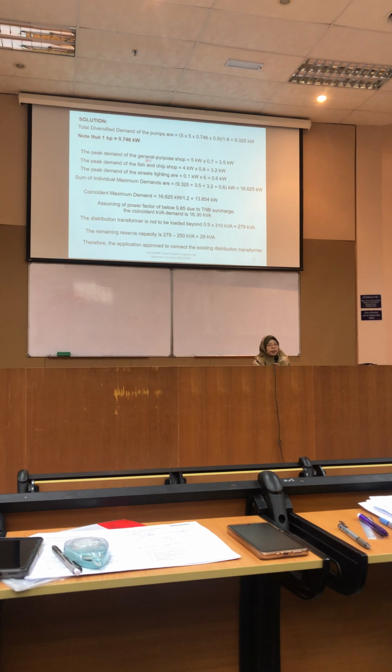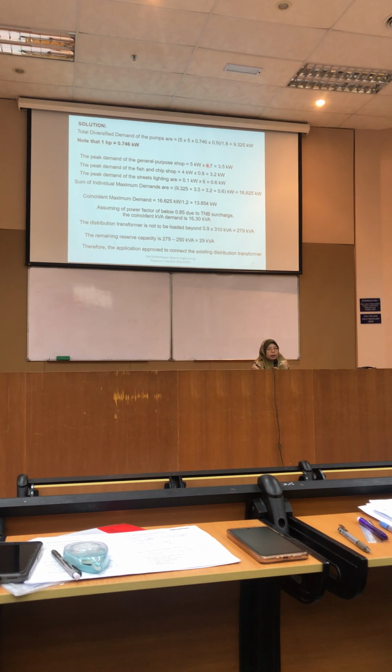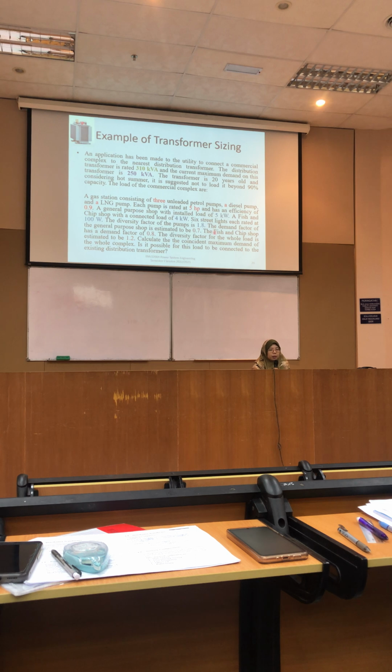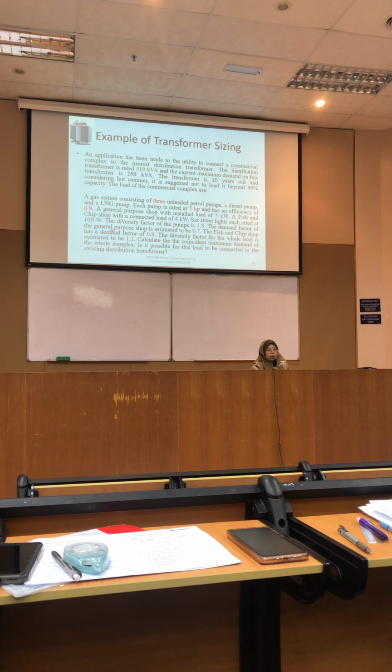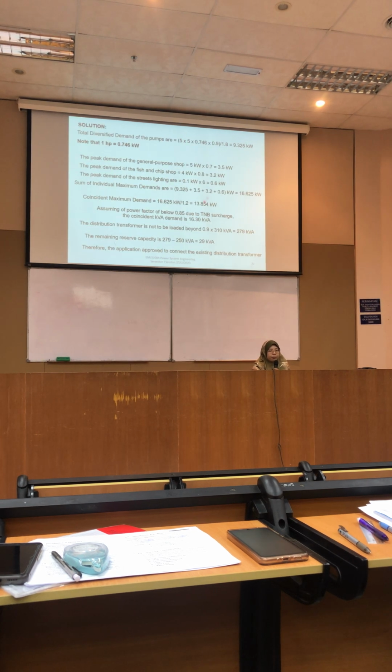The peak demand of the general purpose shop: the shop is 5 kilowatt times 0.7, the demand factor of the shop is 0.7.